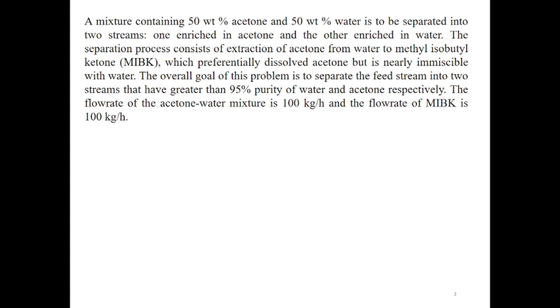Now, the overall goal of this problem is to separate the feed stream, that is the acetone and water stream, such that we get 95% purity of water and acetone respectively. The flow rate of the acetone water mixture is 100 kg per hour, and the flow rate of MIBK, that is methyl isobutyl ketone, is 100 kg per hour. So I would like all of you to start the simulation and complete the input of components first, and then we are going to go ahead.